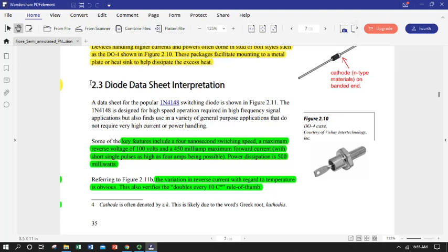They have a fixed voltage, and they can be used in a circuit in a very different way than a resistor. We also included an equation, the diode equation or the Shockley equation, that describes how much current can flow through a diode in either direction depending on what bias we give it, what voltage drop we impose across it at any given temperature, and taking into account some constants having to do with a specific device. So that was that exponent equation that more or less defines the current voltage behavior of a diode.